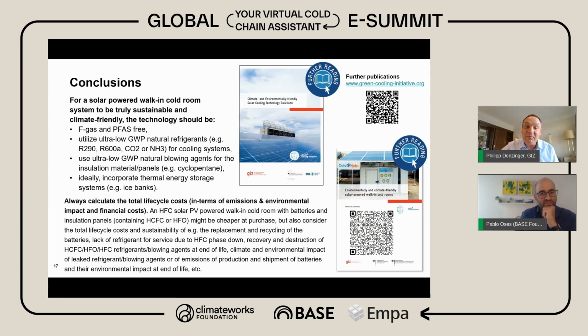Use ultra-low GWP blowing agents, also based on natural blowing agents, and incorporate thermal storage as much as you can. I mean, we have the HFC phase down, and what if you install now a system with R-134a or R-404A? I can promise you, in less than 10 years, there's no more refrigerant available, because these are the first refrigerants that will be phased out. And so what can you do then? You cannot service the system anymore.